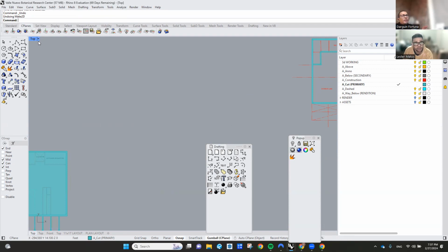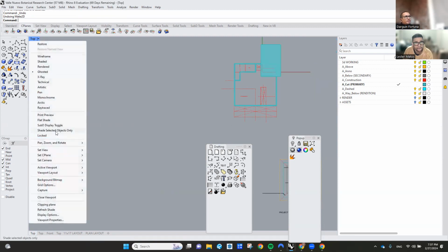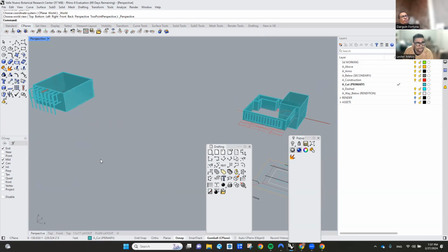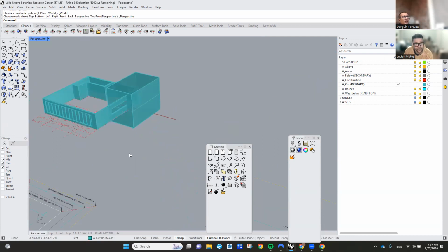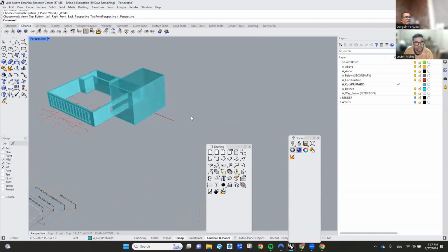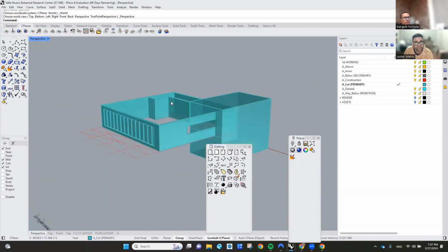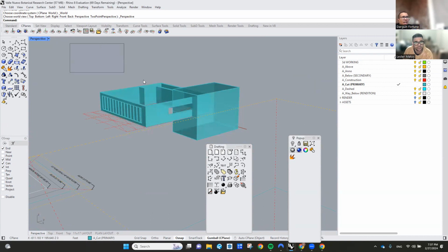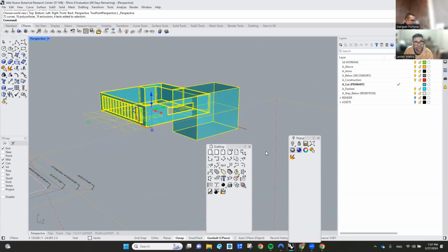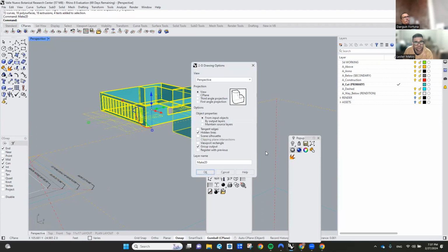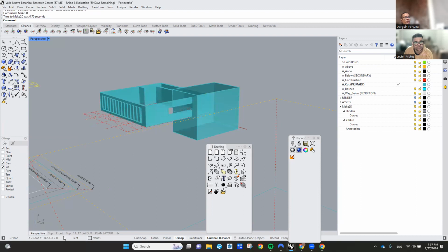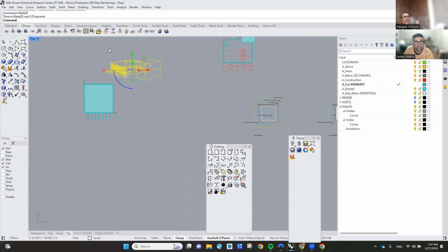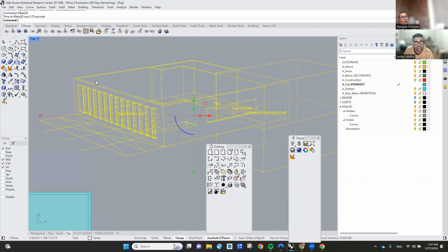Yeah, everything. So what I mean by that is that you could go here and create, let's say, a 2-point perspective. Let's do a 2-point perspective. And I'm going to say, this is what I want to see. By the way, disregard all the mess, and I go here and select that. Then you say make 2D. Enter, enter. You always will do it in top plan, by the way, but you go in top plan and you already have a line version of that. You can bring that into Illustrator, which is what everybody does, and you can create very nicely looking and sexy axon or perspective.